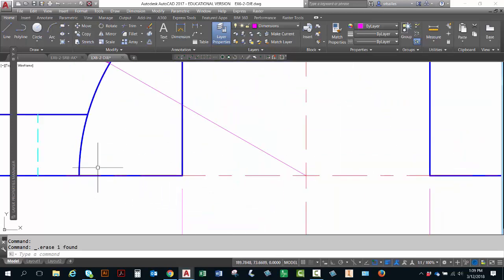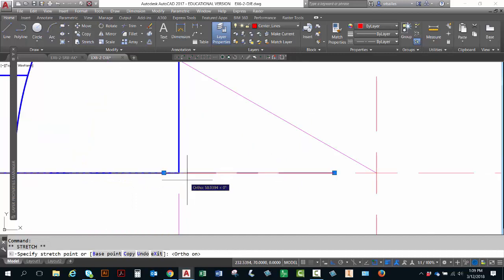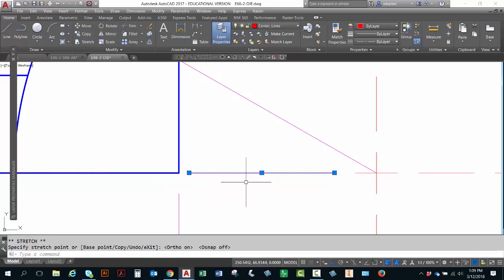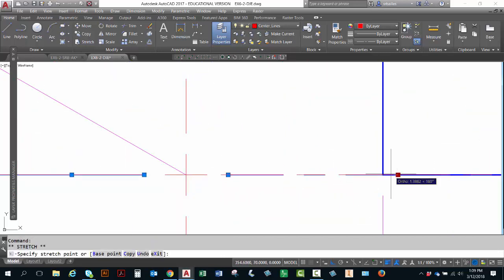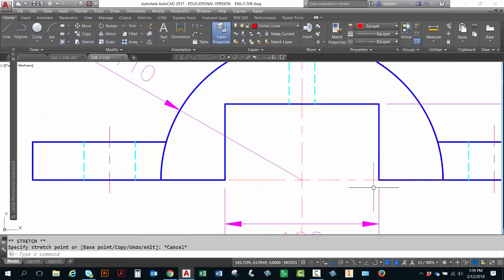Now we don't want to overshoot here, so we need to actually shorten this up all the way and turn on my ortho and turn off my O snaps so that I don't hook it up to anything. And I want a slight gap right here. And if there's not enough room, whoops, let's see, that should be something else.